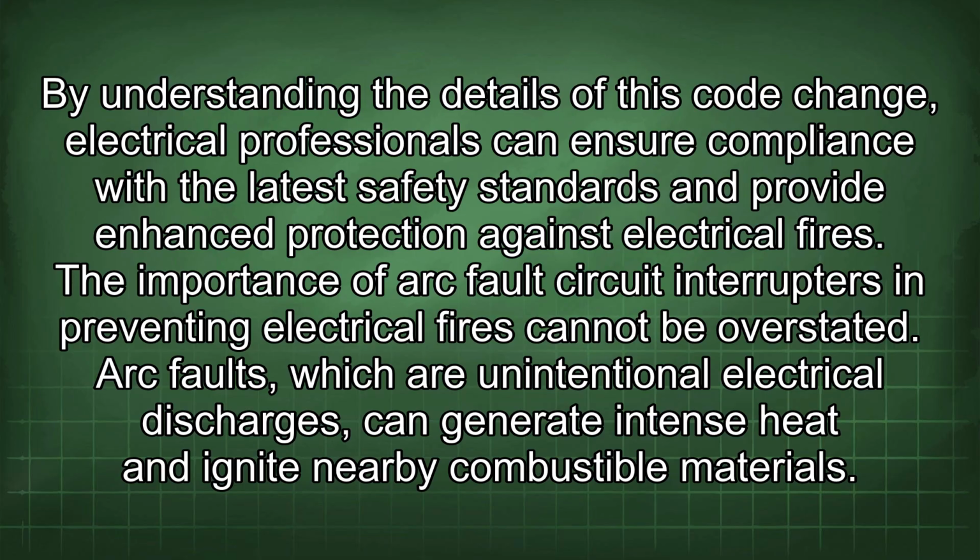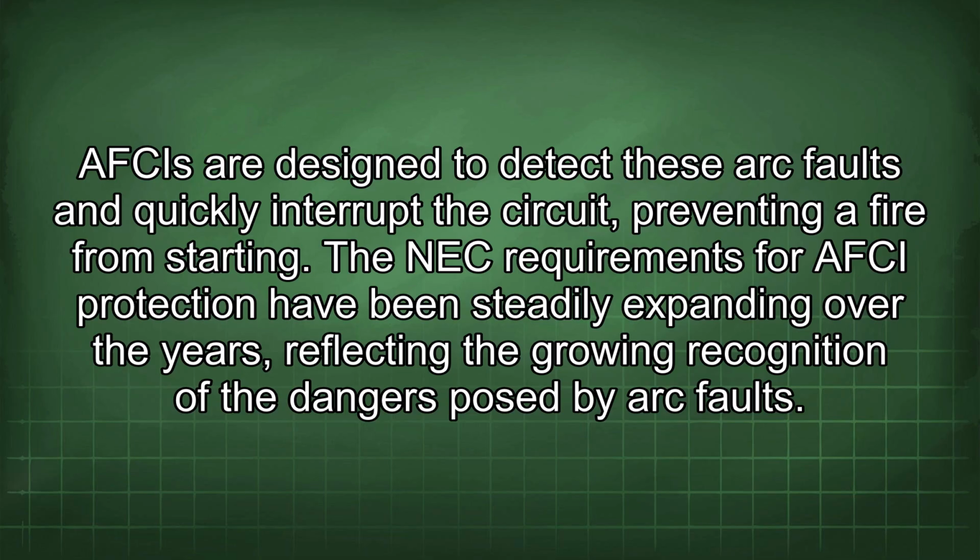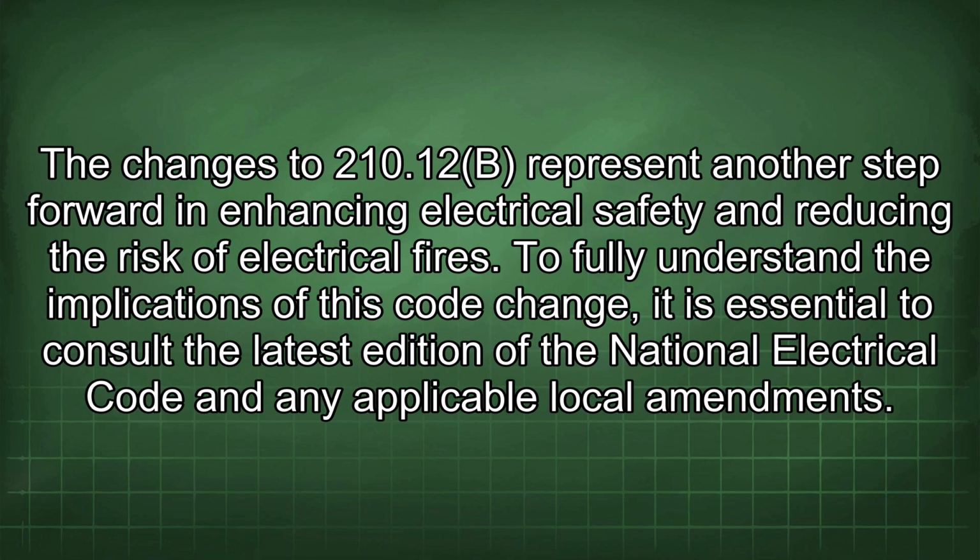The importance of arc fault circuit interrupters in preventing electrical fires cannot be overstated. Arc faults, which are unintentional electrical discharges, can generate intense heat and ignite nearby combustible materials. AFCIs are designed to detect these arc faults and quickly interrupt the circuit, preventing a fire from starting. The NEC requirements for AFCI protection have been steadily expanding over the years, reflecting the growing recognition of the dangers posed by arc faults. The changes to 210.12(B) represent another step forward in enhancing electrical safety and reducing the risk of electrical fires.